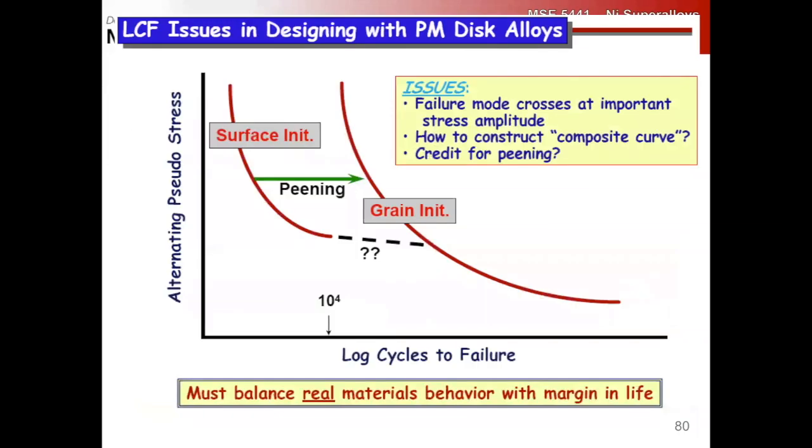So I mentioned peening before, right? So these low cycle fatigue cracks will either initiate at an easy inclusion. If there are no inclusions, that's great, because that means they'll initiate at the surface, right? And this is the log cycles to failure, right? Again, highly schematic, but you can see simply peening really increases the resistance to crack opening, right?